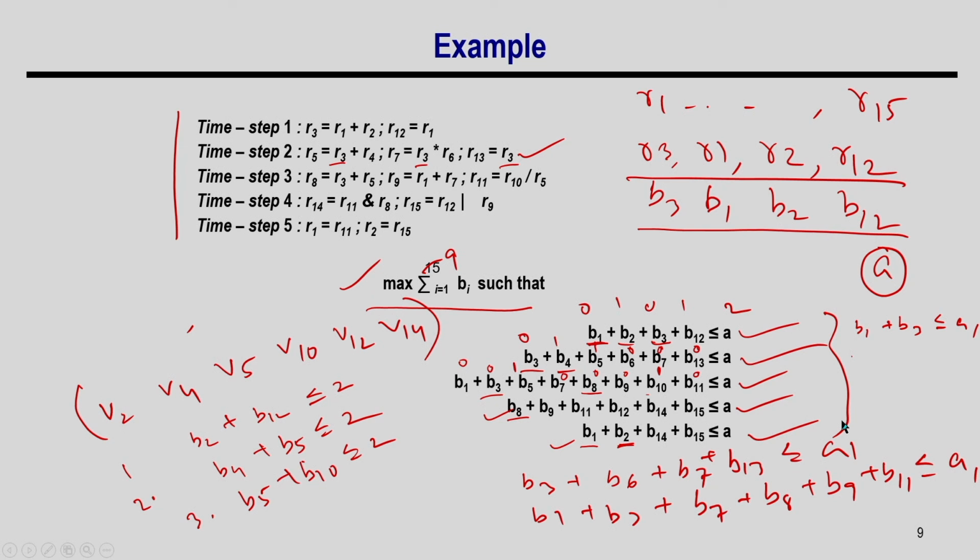Okay. So, this is how I am going to solve the problem. Once I get the mapping, I will again remove those variables from the register constraints and solve it for register bank 3 and so on. This is how I will identify how many register banks are needed and, for each bank, what variables we are going to map.